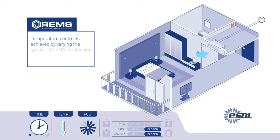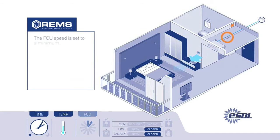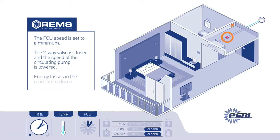Temperature control is achieved by varying the speed of the FCU motor until the required level is reached. The speed is then set to a minimum to maintain airflow whilst the two-way valve is closed to divert the circulating cooling fluid from flowing through the fan coil, lowering the speed of the circulating pump and reducing energy losses in the room.